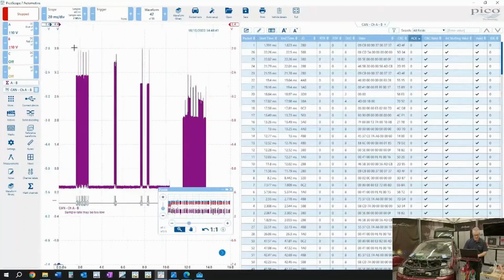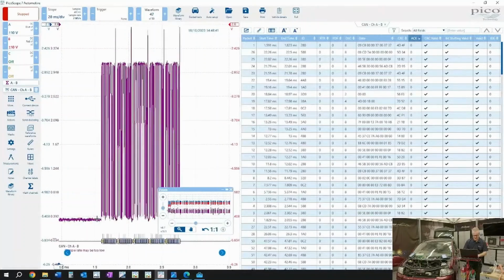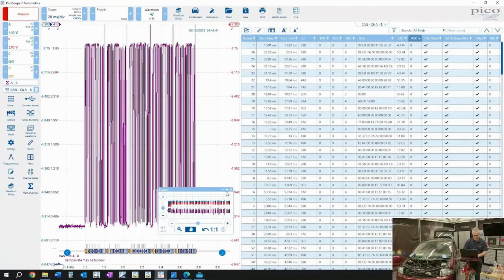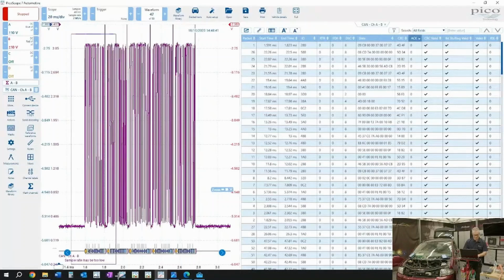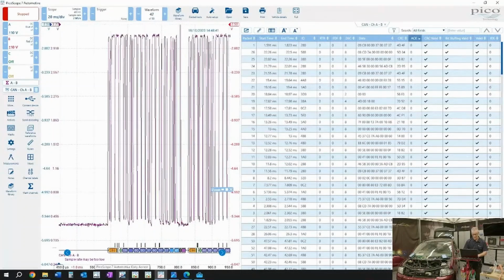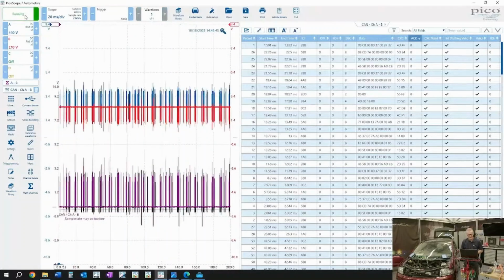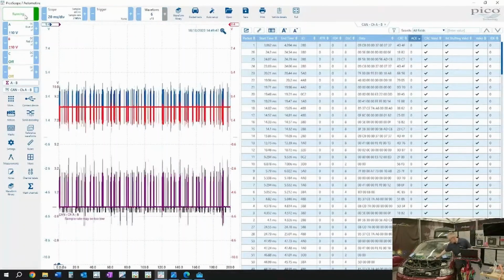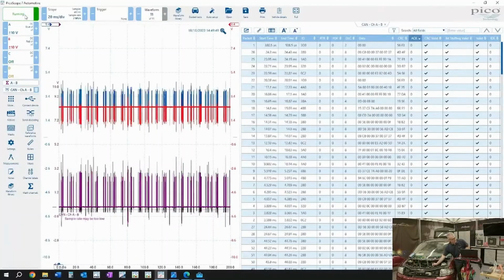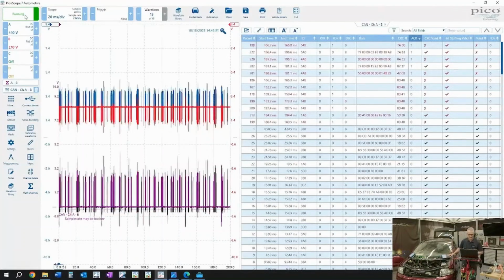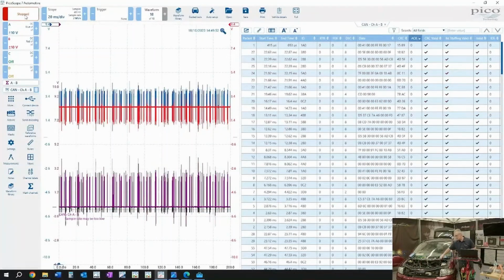I mean, this is testament to fault-tolerant CAN, isn't it? That there I am putting a momentary short on the network, and yet that did not result in a failed packet. No, okay, well, I'm not having it because I'm going to make that work because it worked in rehearsal. Let's do that once more. So let's go for a short, a momentary. Yes, I saw it. So not only did I see the short, but I saw the actual packets of red data. So let's go back.